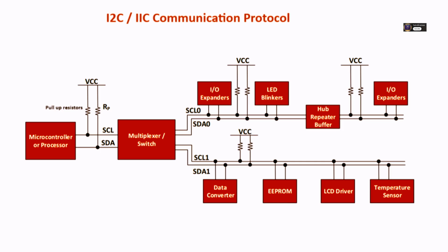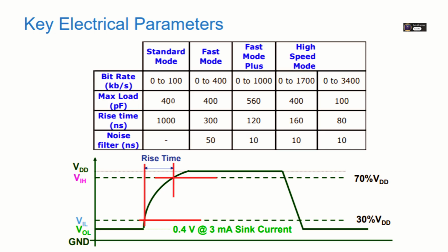So that bus capacitance is a really key factor then. More capacitance equals slower rise times. Absolutely. Higher capacitance from longer wires or more devices directly slows down those rise times. There's just more stuff the pull-up resistor has to charge. The official I²C spec actually limits the total bus capacitance, typically to 400 picofarads for standard 100 kbps operation. If you go over that, you'll likely need stronger pull-ups, with the potential downsides we just mentioned, or, more realistically, you'll have to lower your communication speed.